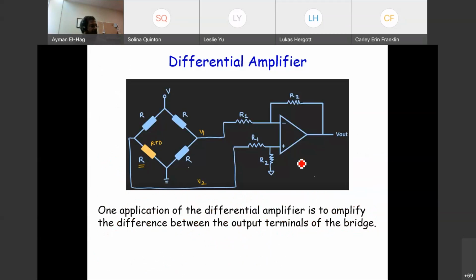to the instrumentation amplifier. Now, this looks familiar to us. This is a Wheatstone bridge. And this Wheatstone bridge could be using an RTD, one of the temperature sensors. So we have here V1, we have V2, we have R2, R1, R2, R1. And remember, the output of this is nothing but the Wheatstone bridge, if you recall. So the output that we have, measuring V out, is the difference actually.